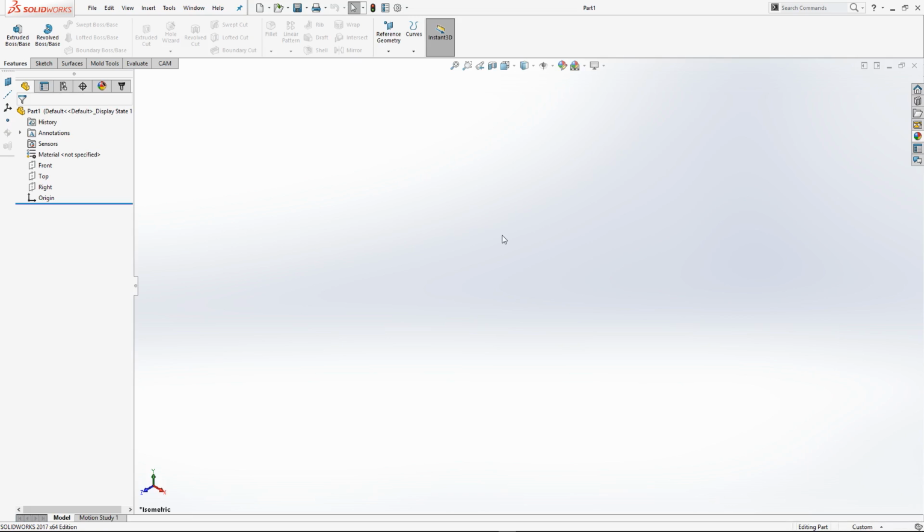Okay, so yeah, workspace is where your 3D model will be displayed. The function tree here contains all your building features in order, from the earliest on the top and the latest below. For assemblies, the function tree will contain all the parts that form that assembly if you've got an assembly open. The topmost of the function tree will always be occupied by default features, such as what you can see now, which is the front, top, and right. They will always stay at the top.